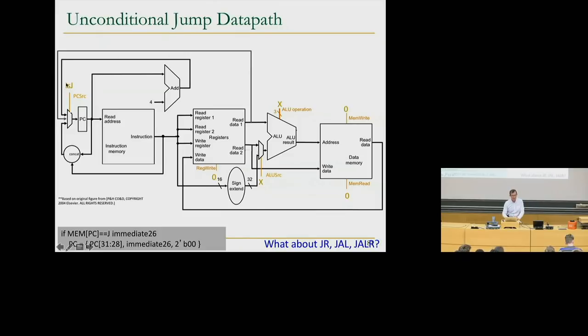Now this becomes more complicated. It cannot be just is jump. Now this is a 3-input mux. You have 2 bits to select. So if you're executing a jump register, this should be the input that you select. So now you add more control signals to be able to do that.